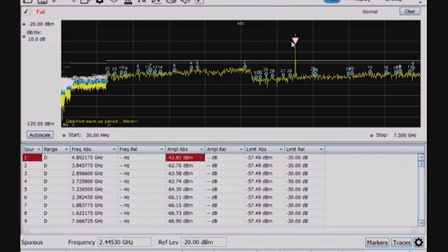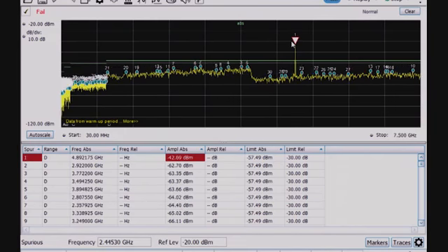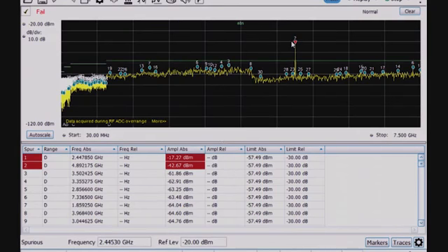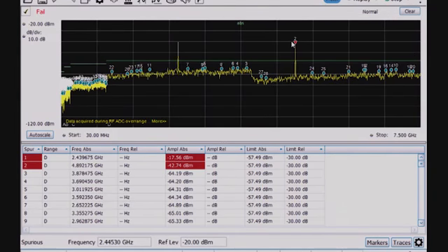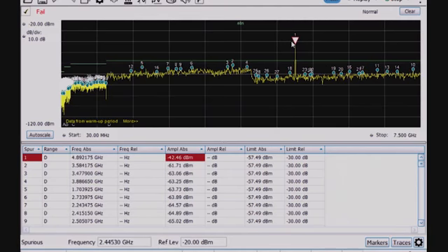But in general, a CISPR peak-based search is a much faster and more conservative test to make sure I have good confidence to get past final EMI compliance, so I don't waste time in the compliance lab. I can figure this out on my own bench, provided I have enough shielding and no other signals present that might cause me to fail the particular test.